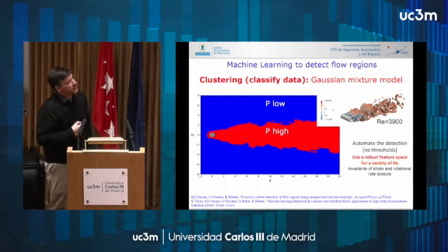One of the things we are doing these days is trying clustering, for example, to determine the viscous and turbulent region after this cylinder. Then, by knowing where this interface is, we can throw a high polynomial order in the zone of the action where turbulence is going on, and here there's nothing happening, so we throw a very low polynomial order. And we can do that with clustering.